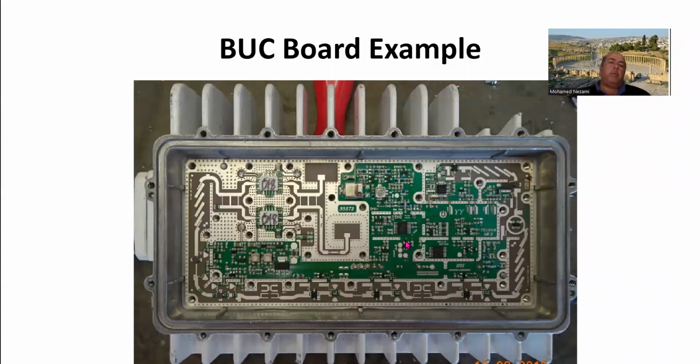Now, here's another example. Likewise here, you can see one polarization here, one polarization here. Or it could be actually they're both the same polarization but different. That's for redundancy probably. So again, in here, your signal comes out. So let's see where we start. We start right here. This is probably the LO signal. Here's the LO band pass filter, and then we go out here. This is a mixer.